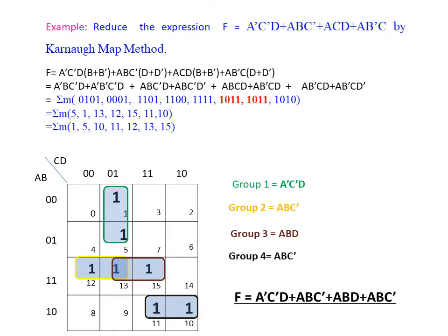We are grouping into one cells, so we will get only one variable elimination in each min-term. For this cell grouping, the answer is A B bar. The common between these two is C. And for this yellow cell grouping, A B, the common is C bar.